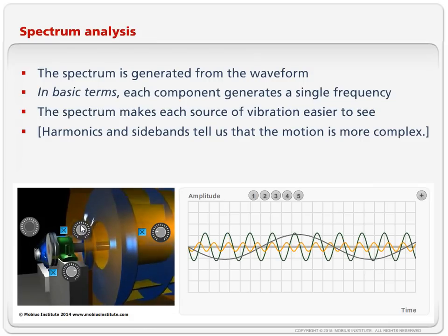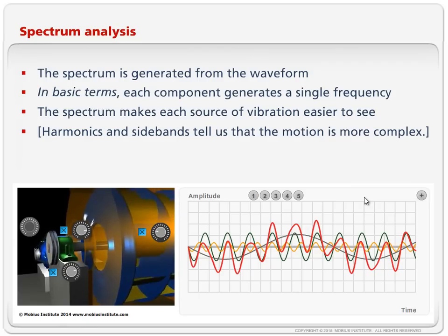Unfortunately, this is not exactly how it works, because we don't see those three nicely coloured signals, we see the summation of all three. They add together, they combine to make the housing of that bearing move according to this red line, and that's what the sensor feels. That's what this accelerometer feels, and that's therefore the signal that goes up to our data collector.